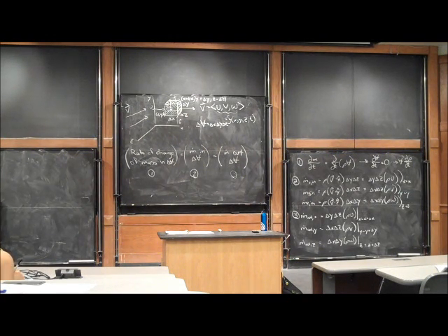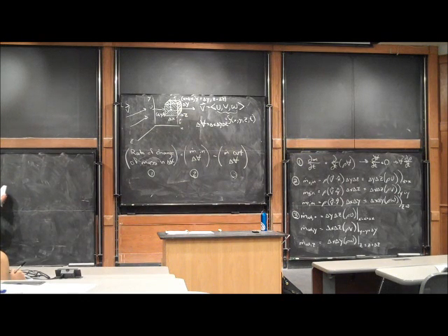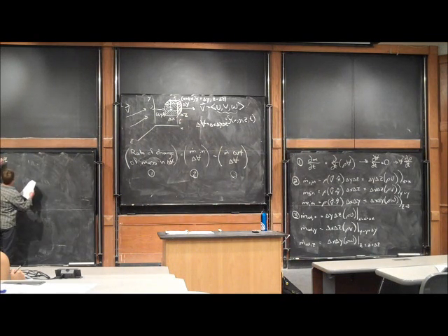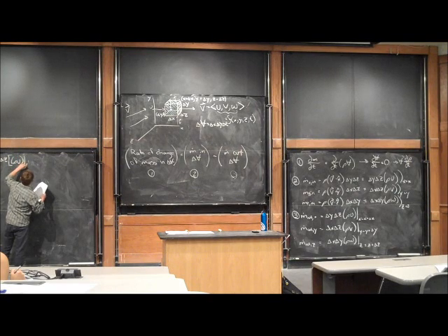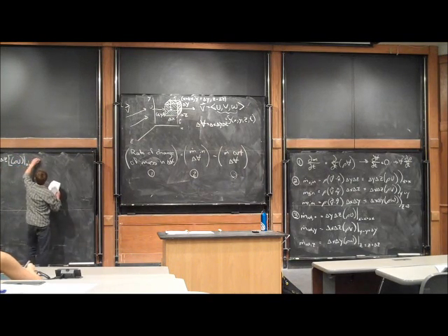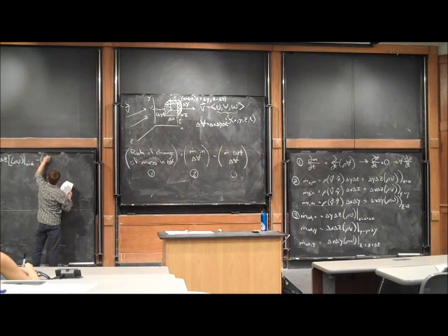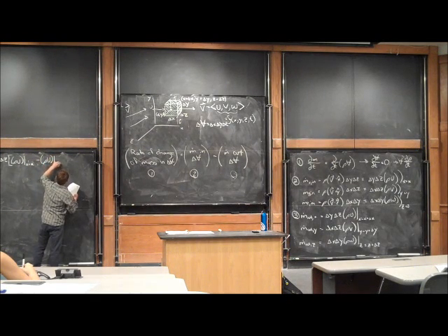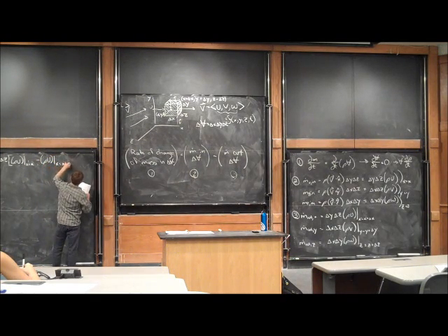It's got to be equal to the mass coming into the system, which in this case we defined as, let's see, delta y, delta z times rho u at x is equal to x minus rho u at x is equal to x plus delta x.